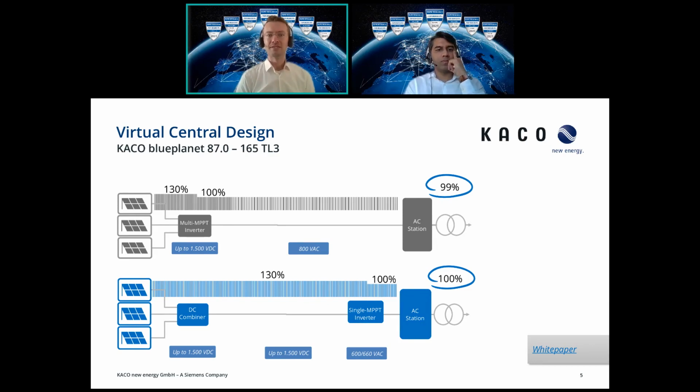When we talk about large-scale PV projects, utility projects, we generally have an overloading on the DC side. A DC-AC ratio of anywhere between 120 to 140% is relatively common nowadays. We've used 130 in this example. And maybe one point first: why do we overload these projects?